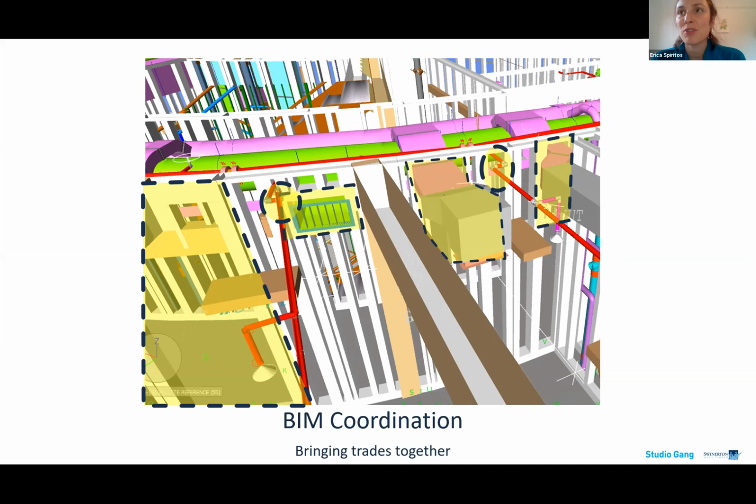And so that process, when people ask, what's the lead time associated with mass timber? So much of that is related to this process. Like how long does it take to figure out exactly what we need to fabricate, especially for jobs of less than 100,000 square feet. Usually the bulk of that lead time is associated with this shop drawing or detailing process where we are building the structure, where we're constructing the whole building in a virtual setting, rather than the bulk of that time being consumed in the manufacturing facility.